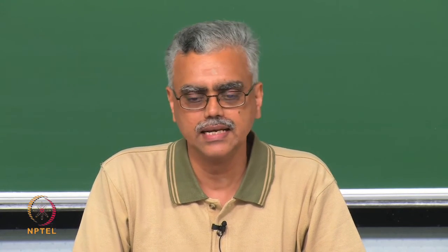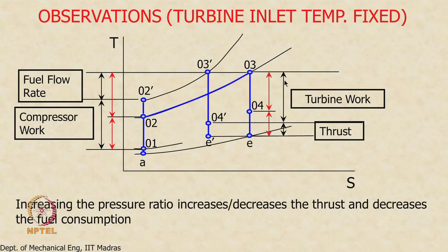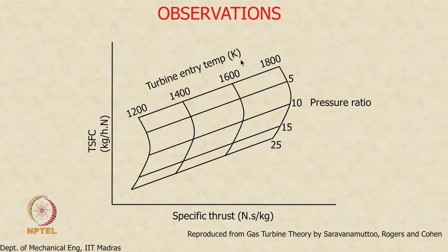Any questions? Yes. Why is the specific thrust increasing again? This is a thrust per unit mass, and that has to do with the way these curves diverge. When these are close here, we are getting momentum thrust, but we are also getting some pressure thrust from here. So the sum of the two, because we are now operating with different conditions, can actually exceed what we had previously.